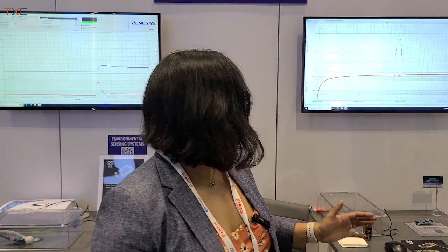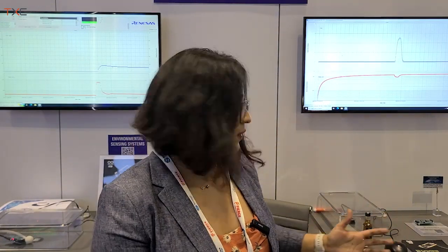On my left side, you have this one here that's the TVOC sensor. VOC is volatile organic compounds, present in a lot of different contaminants that you can find in indoor environments. It could be in your cleaning agents, in alcohols, in formaldehyde, like refrigerant leaks. So there's a lot of different chemical pollutants that are present, and this sensor can pick that up, and it can do demand control ventilation for you.